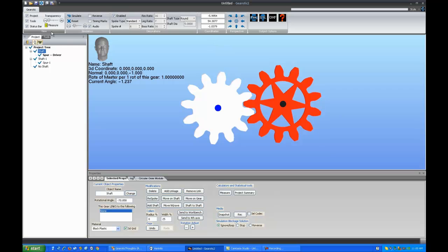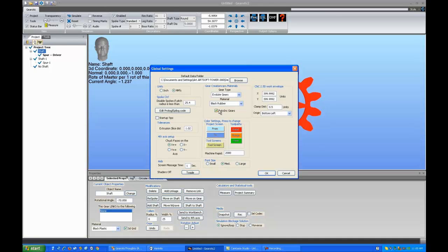And while we're on that topic, up at the top left side of my screen, you'll see there's a bunch of little buttons that are icons for various operations like new project, load a project, save a project, save as, and there's a little gear wheel that says options, and this is where, if we bring it up, you can set options, such as the size of your CNC table. This is used in the CNC Workbench. You can set a clamp distance, which is the distance around. All these things are explained in the 2.5D CNC video, so I urge you to watch that